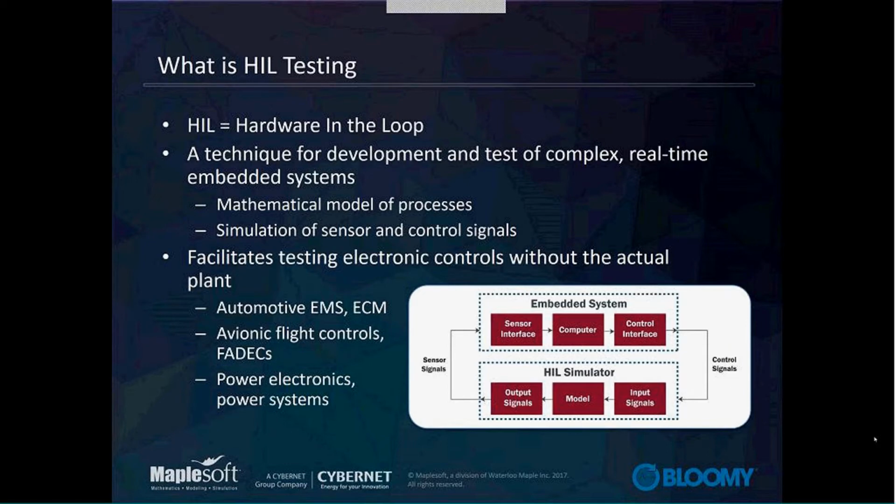It's essentially a technique for developing and testing complex real-time embedded systems, of which the BMS is the case. And we're using mathematical models, physics models, essentially models to replicate what the actual product itself is doing. So instead of using an actual battery cell to simulate the pack, to operate the pack and test the BMS, we're actually using a simulation, and it allows us to do the testing much more effectively and reliably.